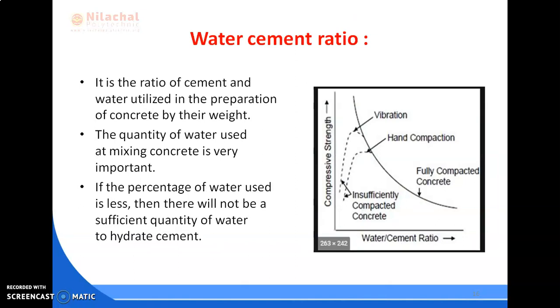Also, the addition of more water gives a dilute paste, which has more pores at the micro level. This makes the concrete weak and results in shrinkage, cracks and different issues. As I already said, too much water also results in segregation or bleeding of aggregates and gives porous concrete of low strength and low density.